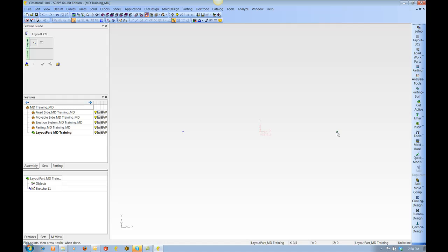So I'm going to put one here, one there. See, I'm at step 1. I middle click. Now I can put in some rotational values here. I think this one needs to be 270, and this one needs to be 90. I can also affect the Z position of the part here. I can raise it up or lower it down.